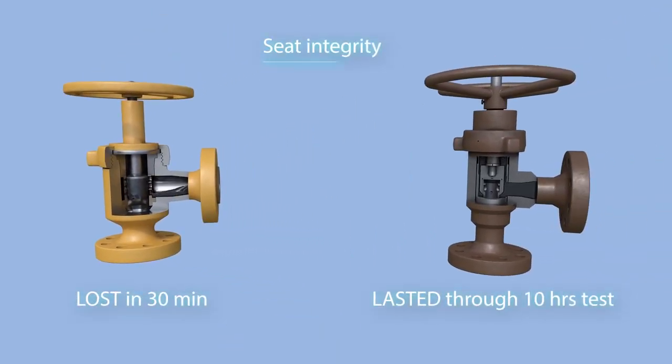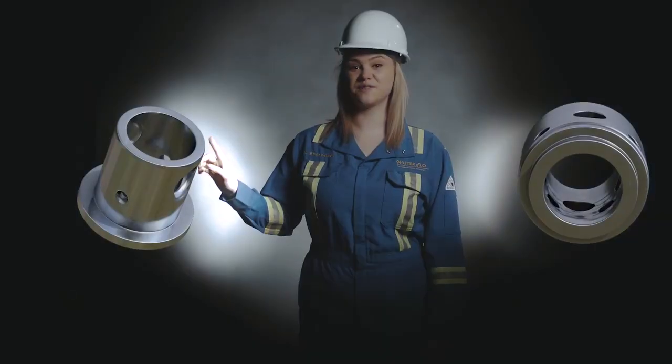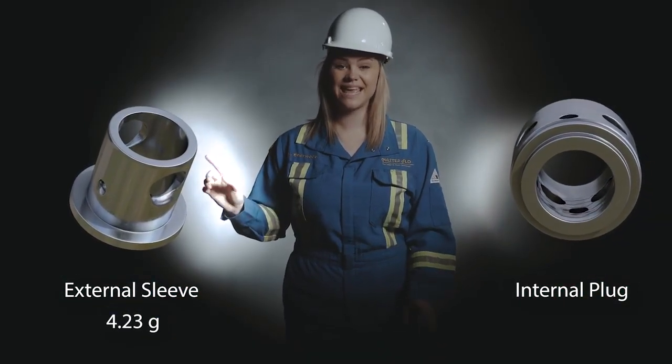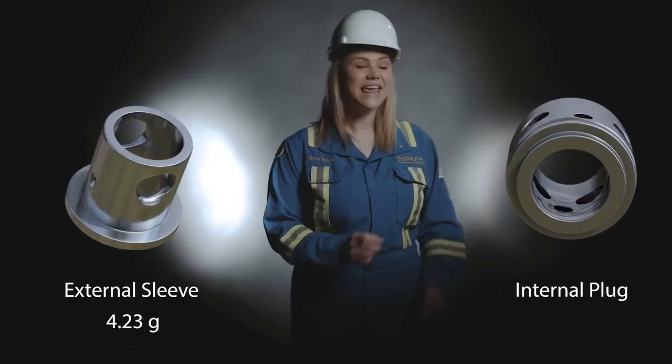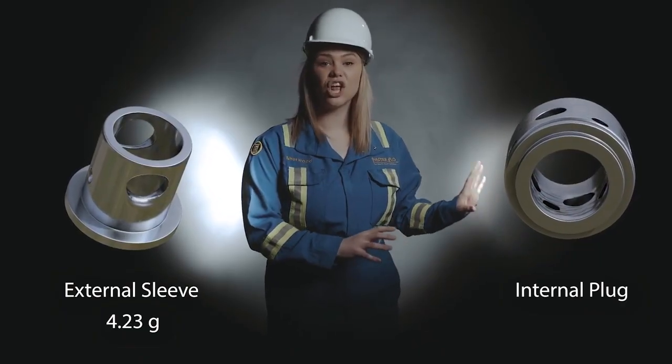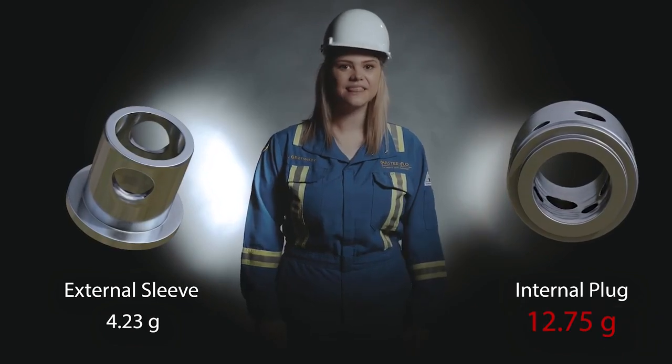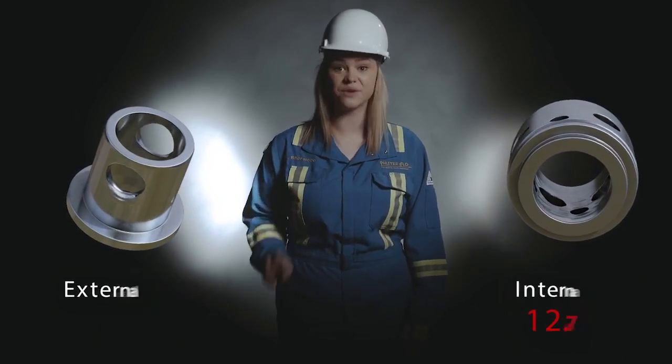The external sleeve seat feature was outside of the cage, away from the high-velocity turbulent fluid zone, so it lasted throughout the 10-hour test. This valve's material loss was only 4.23 grams. In stark contrast, the internal plug design lost an astounding 12.75 grams. That's more than 3 times the material.